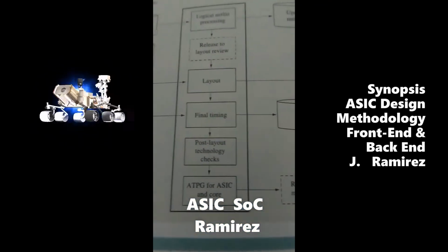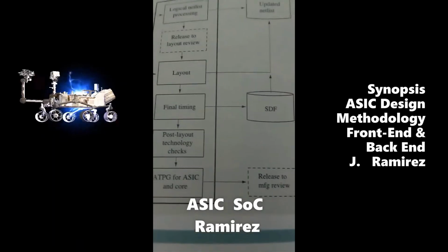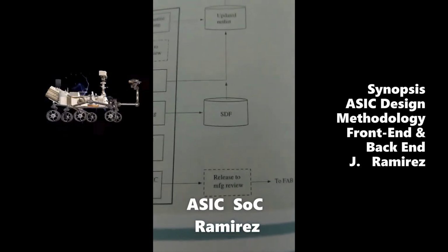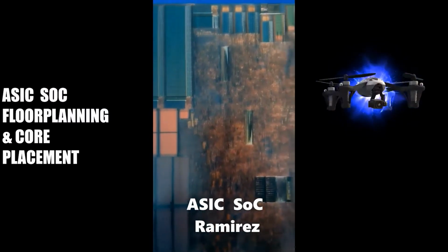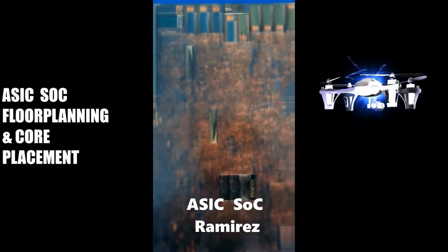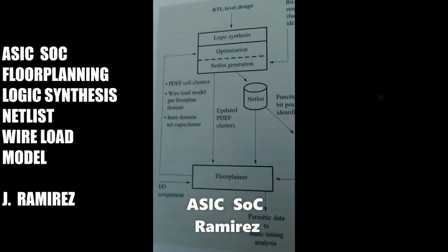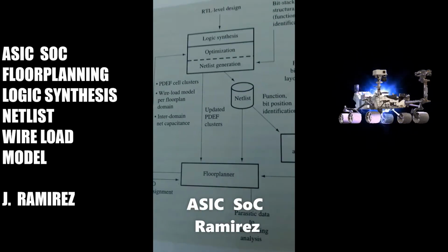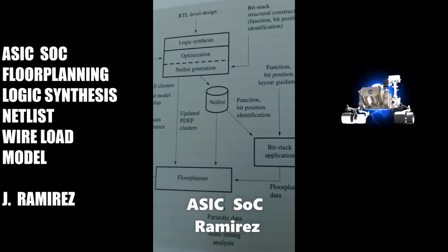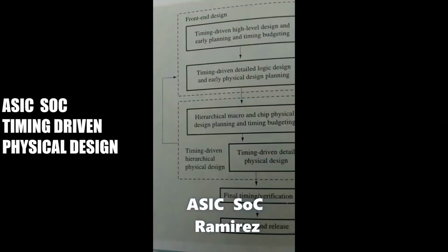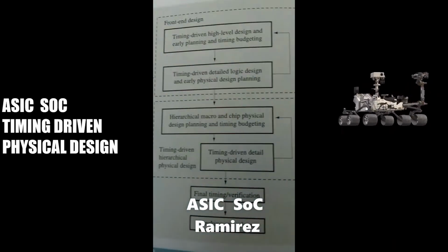The area estimation function described determines the appropriate width and height of each macrocell in the hierarchy based on the wire demand in the X and Y directions, as well as for any child cells or other descendants down the hierarchy that have rigid shapes.